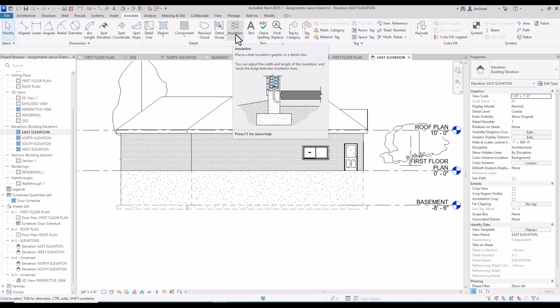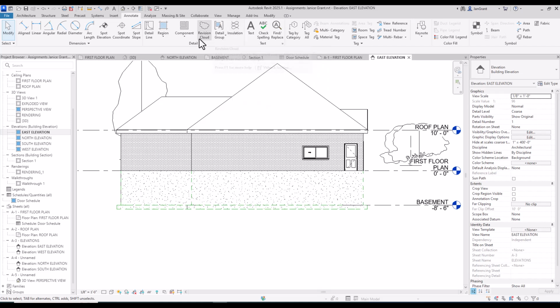So you cut a wall section and then enlarge the scale of it, and draw the insulation and use properties to change the width of that insulation. We also have components that we can draw, and those components would be loaded, like the wood for the top plates and the bottom plates. I'll post a video for that you can look at if you're interested in that.